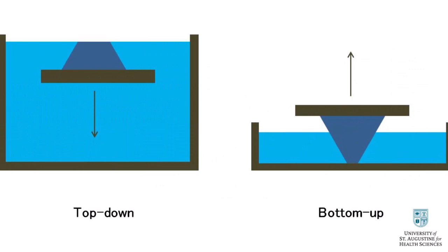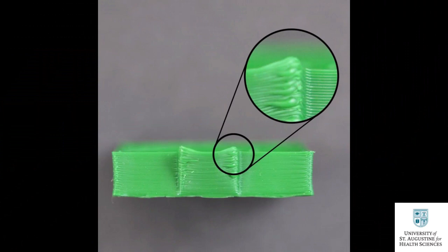These printers have two types of build. The first type is top-down orientation, where the 3D object faces upwards during printing, and the second type is bottom-up, where the 3D object faces downward during printing. Just like warping can occur in FDM printers, curling can occur with SLA printers. So what is curling? Curling occurs when resin reduces in size when exposed to ultraviolet light, which can affect the size of 3D printed objects as it cools down.